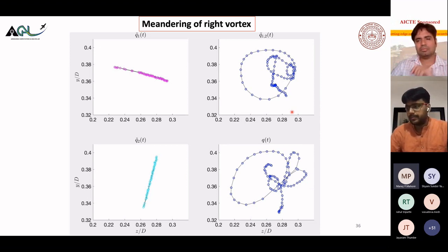You will have the effect of the initial condition in the beginning. The initial condition is not perfect, right? For example, you can start with any random initial condition. Take a lid-driven cavity where the flow velocity is zero; you can instead start with flow velocity equal to 1. Still, you will get the same solution, right?